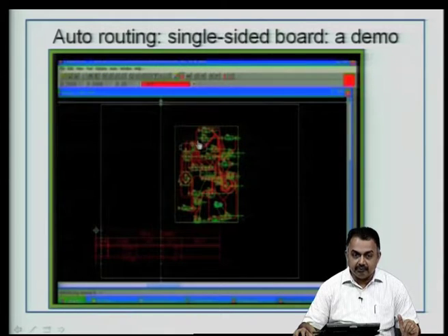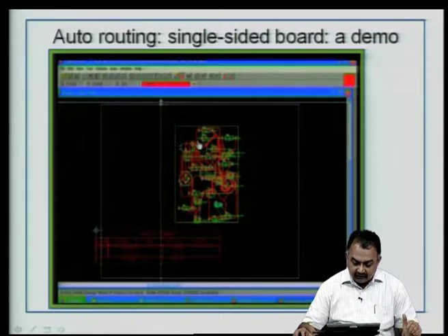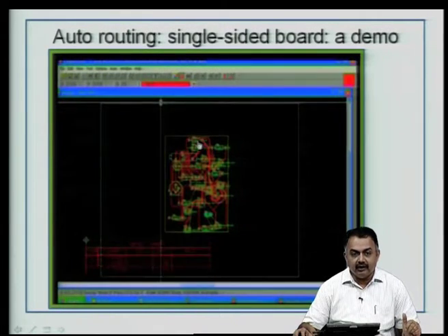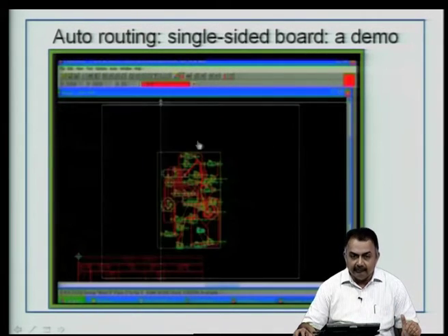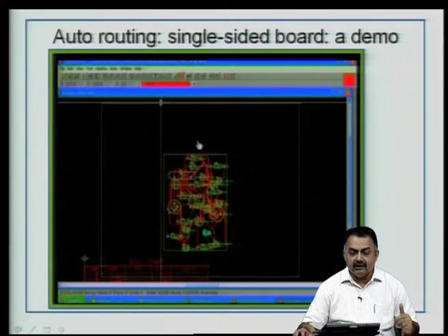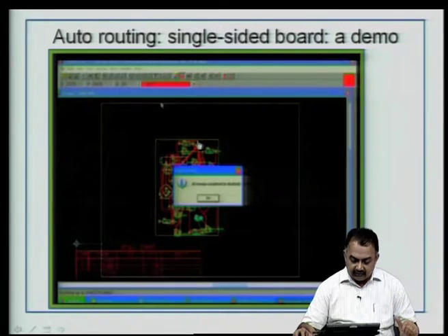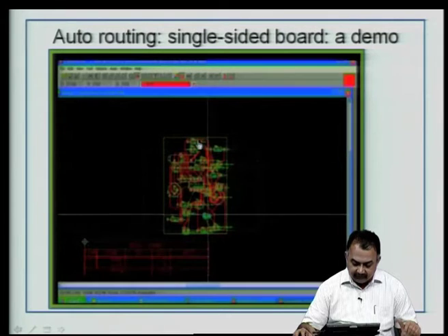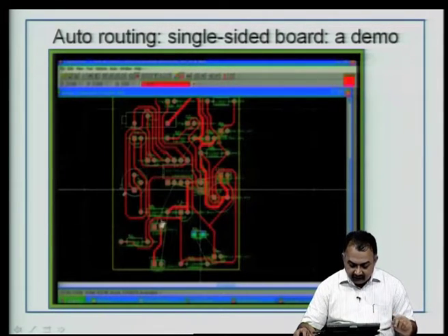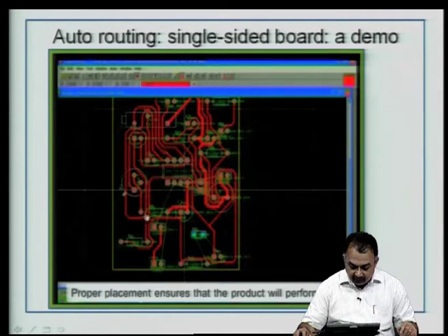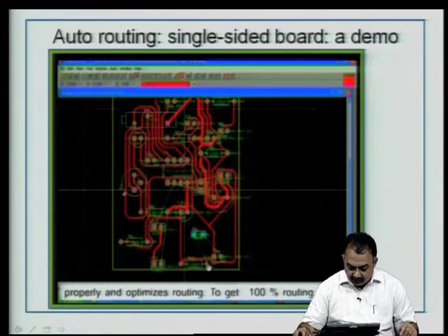You can also expect a few percentages of nets not being completed at all, because the distance of the components are longer. Some of the nets act as obstacles, some of the packages act as obstacles. So, as you can see here very carefully, some of the nets are not routed. For example, this is an unrouted net, this is an unrouted net. Now, this is an unrouted net.